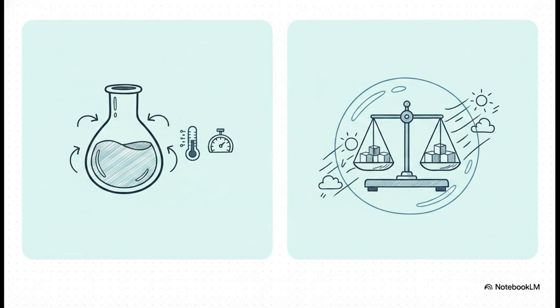See, it's absolutely crucial to grasp that volumetric flow is entirely dependent on temperature and pressure. It's usually measured in units like milliliters per minute or cubic meters per hour. But here's the catch. If the temperature or pressure changes, the physical volume of a gas expands or shrinks, right? And that totally throws off your reading.